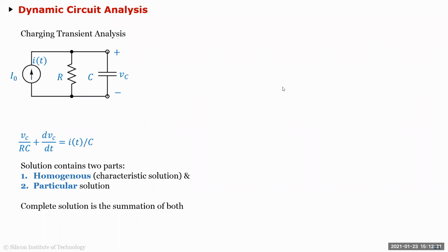Okay, Chandan, I see your question. I don't know if it's a question or a statement: VCVS is analogous to an op amp. It's not exactly analogous, but what I mean is you can model an ideal op amp with a VCVS, where the input impedance is infinite, the output impedance is 0, and the voltage gain from input to output is high. You can make it infinite or high. So you can model it.